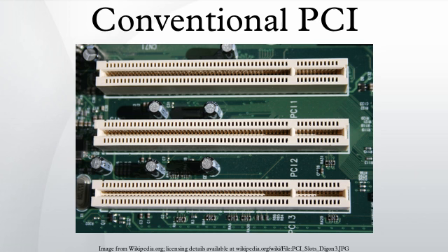On the 5th cycle of the address phase, a catch-all subtractive decoding is allowed for some address ranges. This is commonly used by an ISA bus bridge for addresses within its range. On the 6th cycle, if there has been no response, the initiator may abort the transaction by deasserting FRAME. This is known as master abort termination, and it is customary for PCI bus bridges to return all one's data in this case. PCI devices therefore are generally designed to avoid using the all ones value in important status registers, so that such an error can be easily detected by software.